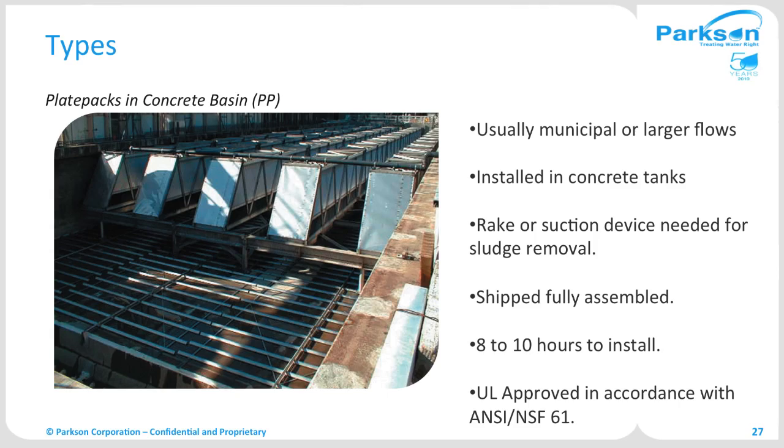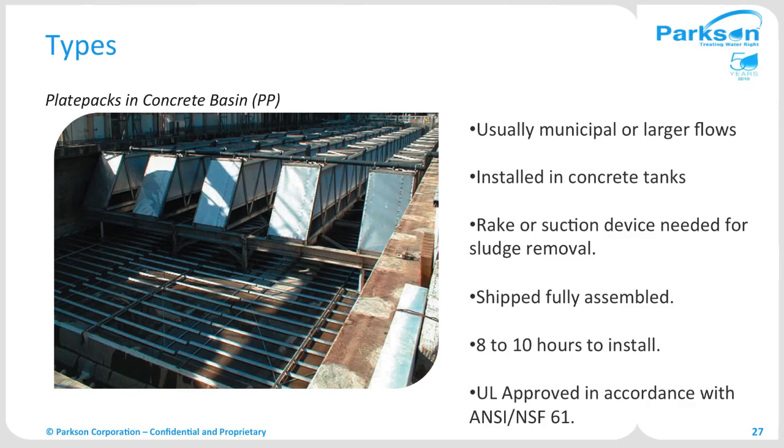And the third type is plate packs in concrete basins. We usually use this model for larger flows or municipal applications. They're installed in concrete tanks. You usually need a scraper or suction type of device to remove the sludge underneath the plate packs. They are shipped fully assembled, and it requires 8 to 10 hours to install. And we have plates which are UL approved and NSF certified.